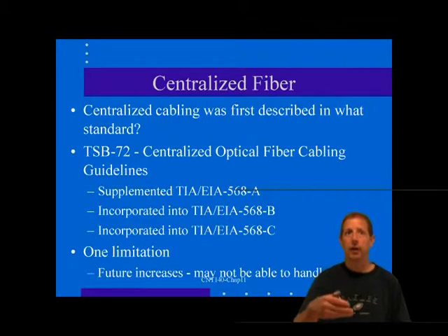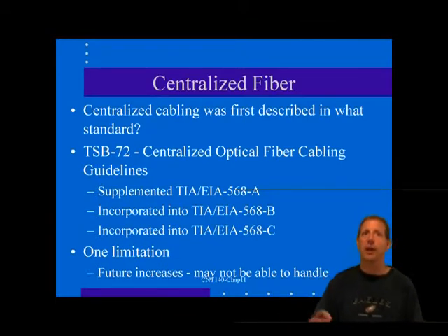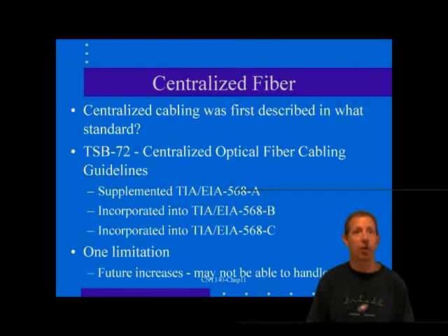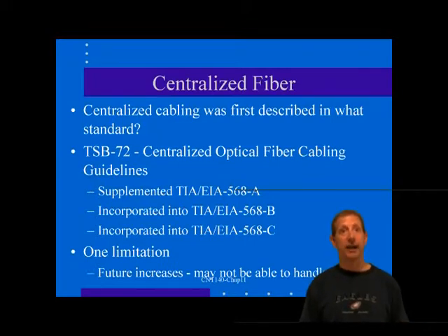In addition, if a blown-in fiber system is used, the multi-cell tubes may be run to the TR, where they are broken out into individual tubes and routed to each work area. Alternatively, loose buffer multi-fiber cables may be run to each TR and then spliced onto individual work area fiber runs. This method avoids the additional bulk, cost, and loss of an interconnection patch panel.